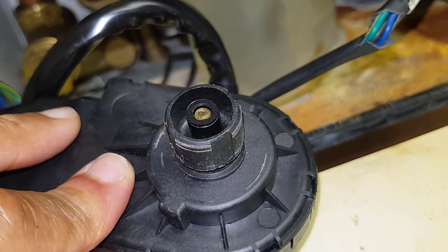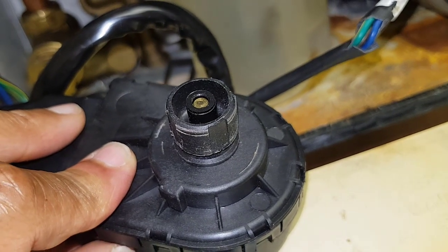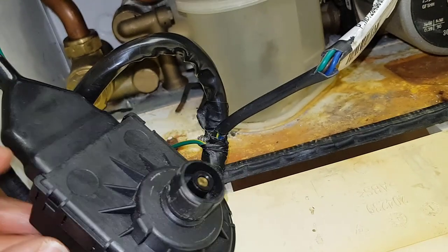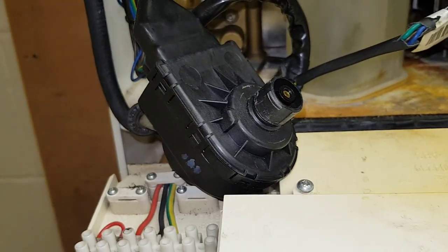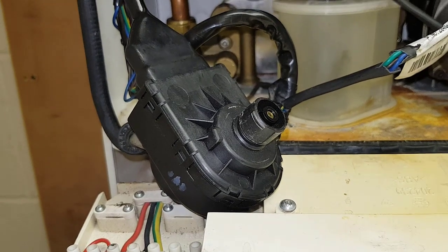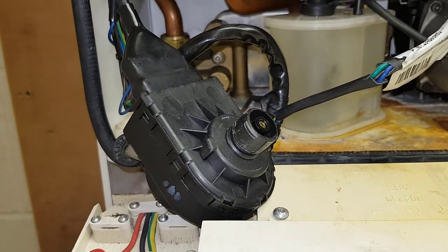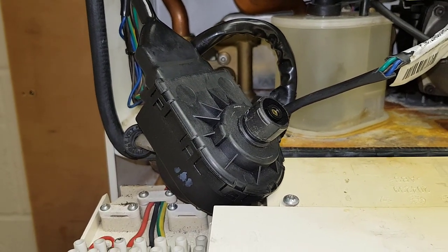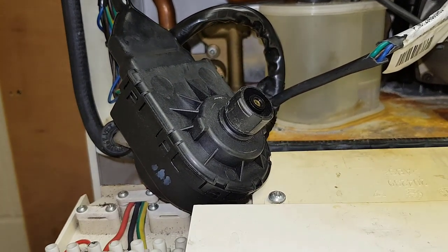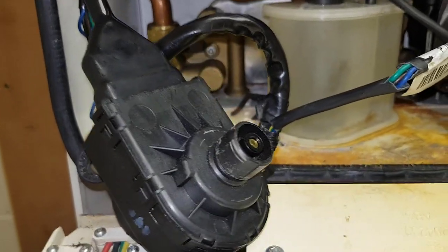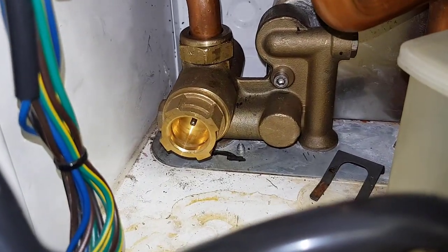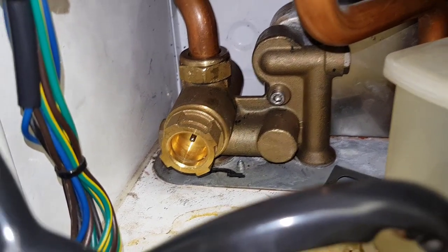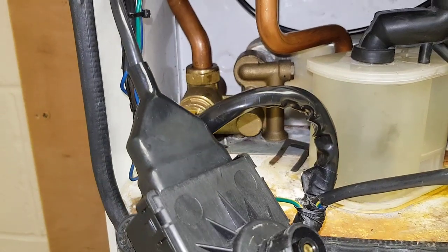So it wants to be out like that for heating and in for hot water. So we can carry out a test to see if it's in the right position on the right mode. Depending on the result of that test, we won't get too deep into it now, that will determine if the problem is the diverter valve cartridge. So we do that and then we'll find out what that is.